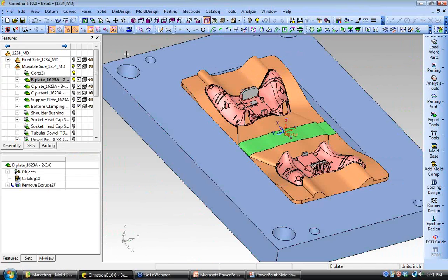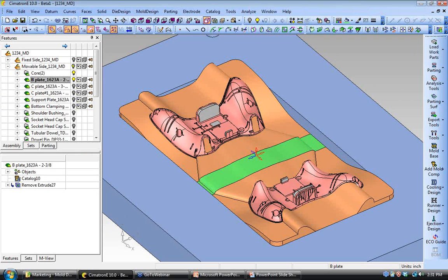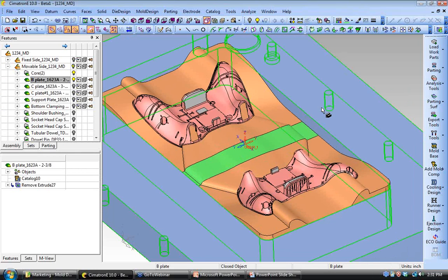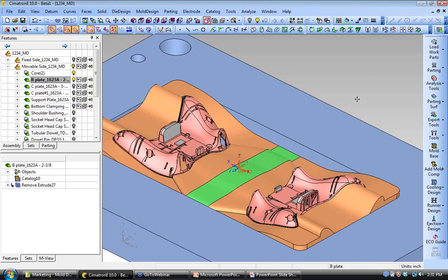So, okay. Now, one of those specific mold functions that I mentioned was for cold runner designs. Runners are created by driving a profile shape along a sketched path. Our design today really doesn't have the need for a long runner, but I can show one to show how the function works.